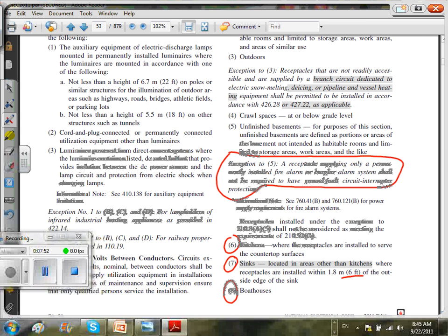Right. I mean, the potential would be you don't put a GFCI outlet there because it isn't accessible. That's a good point. And why should you put a GFCI receptacle when it's not accessible? Unfortunately, you have to have a GFCI receptacle now, and it has to be accessible. So to the best of your ability, when you put your receptacle, it has to be in a location that's accessible. And you can argue, I put it right here, and the owner went and put the freezer right in front of it. But in 2011, they added all these locations, and they must be readily accessible.